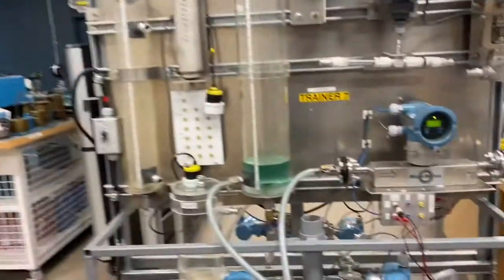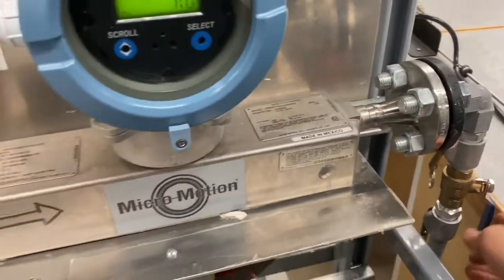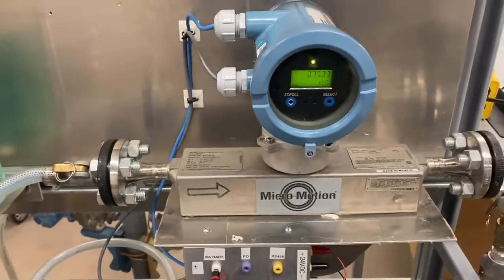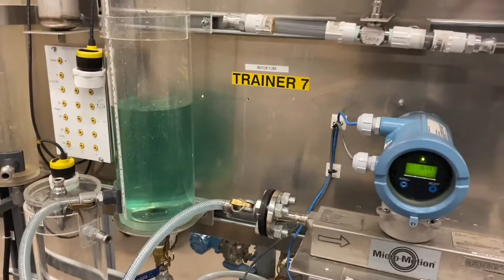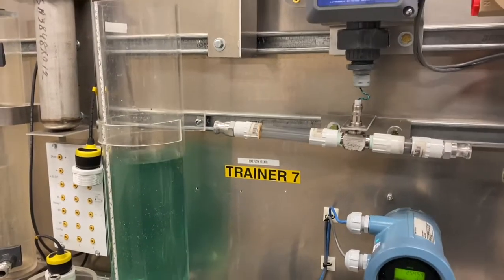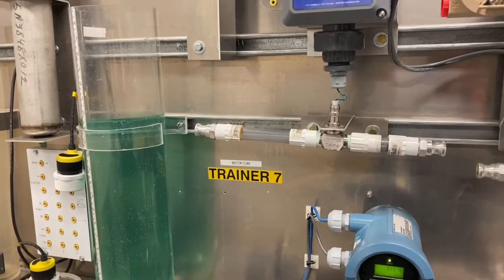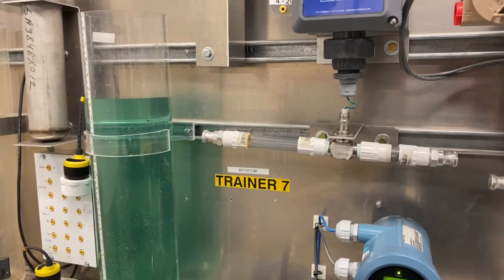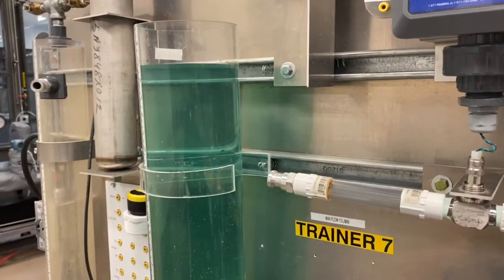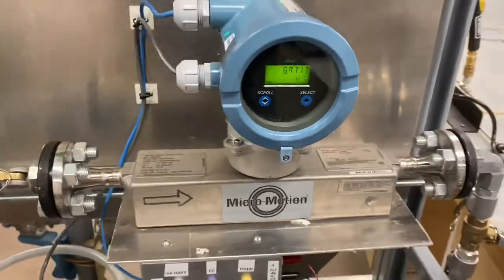I'll just open the valve, and just downstream here, we'll open this quickly. So we have full flow, and you can see that it's recording a mass value there now, a total, and our liquid's rising in our vessel. So once it gets near the top here, I will slam the ball valve shut quickly and record our end value, or our stop value. So that's probably good right there. And there we've got our mass value. It's still kind of catching up.